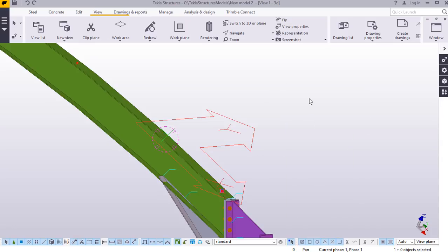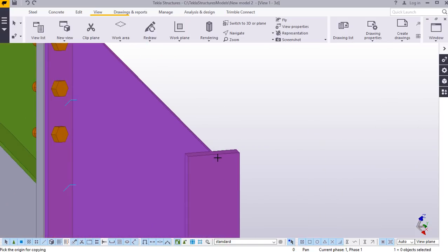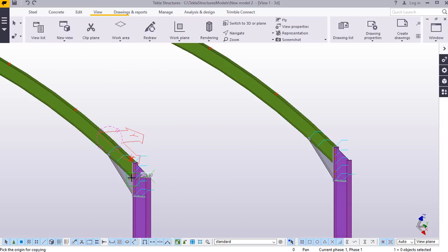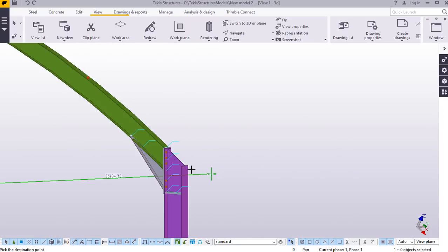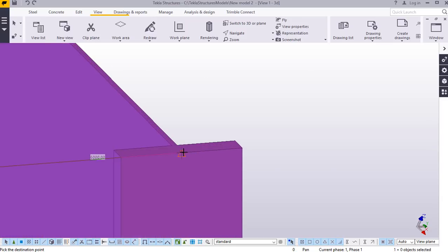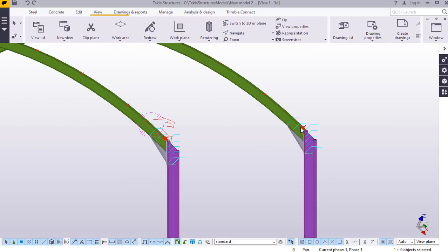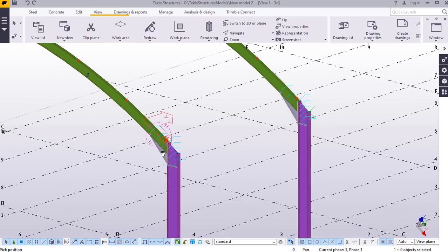Now we want to copy this to the other end of our elevation. I'll pick on this like that from that spot and zoom out and target this end. I'll place it right there, right click and exit from that. Now I'll have my point here. This point will guide me in placing my purlins. Now let's go straight away and start placing our purlins.